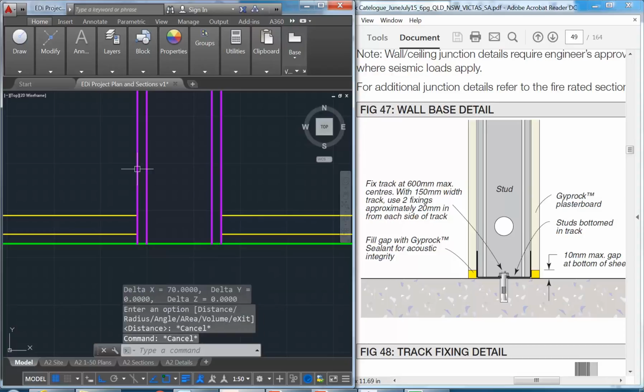You can go down to 57, I think is the smallest. So that'd give you a 77 mil wall, which is handy sometimes. Some pipes will fit, but not for drains. Definitely not drains. For reticulation, like water supply, no problem, they can go into anything like that. But the noise is an issue. So normally you want to make them a bit deeper because the depth does help with the sound reduction.